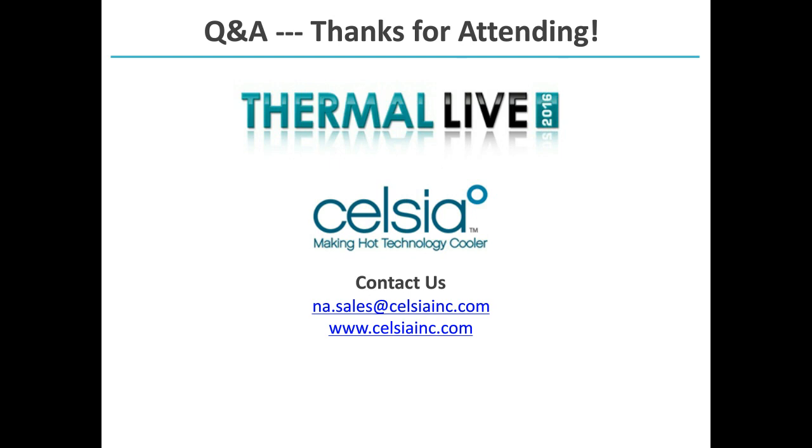Yes and no. In other words, if we go through the calculation and I tell you what its effective thermal conductivity is in a watt per meter K number, then CFD is a perfect place to do it. If you're trying to model the liquid flow in the wick structure, the boiling flow at the surface of the wick structure, and the vapor flow in CFD, that's a bit more challenging.